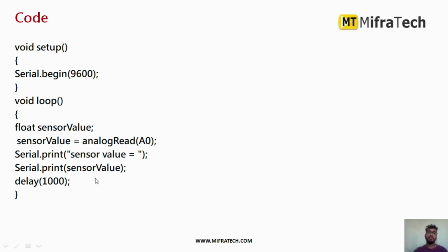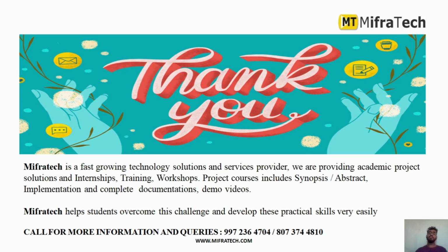If I execute this code and upload it to the Arduino microcontroller, the gas sensor will detect whether any concentration of gas is there or not, and it sends data to the controller. Like this you can easily interface this with the Arduino Uno microcontroller or any other microcontroller. In this way you can make use of this MQ7 gas sensor to detect combustible gases which contain carbon monoxide in particular.